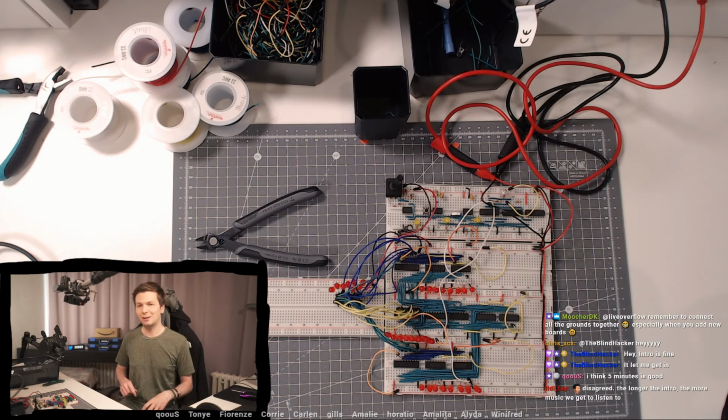Anyway, so what happens now if we execute the clock? Currently it's configured in a way that this register has the input enabled, so it will read anything that is currently on the bus, and the ALU is outputting its result on the bus. So right now, if you look here in the register itself, it's 1111, so the highest value, but on the bus it's already -1.